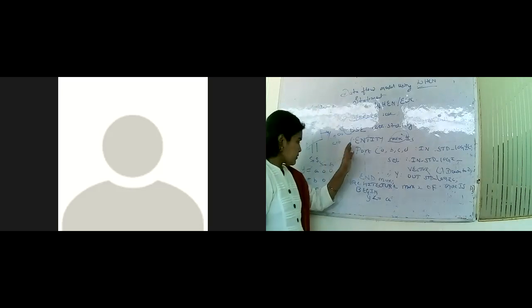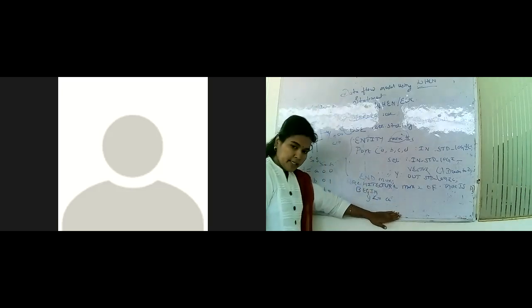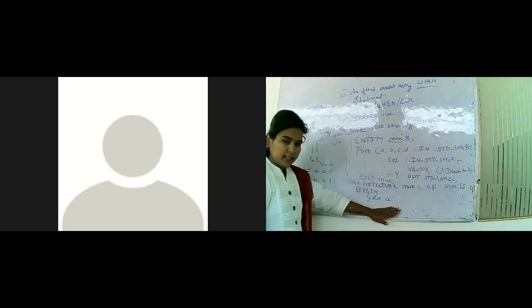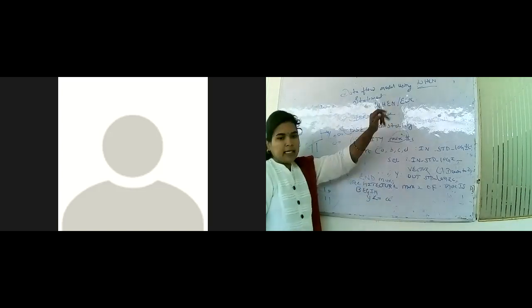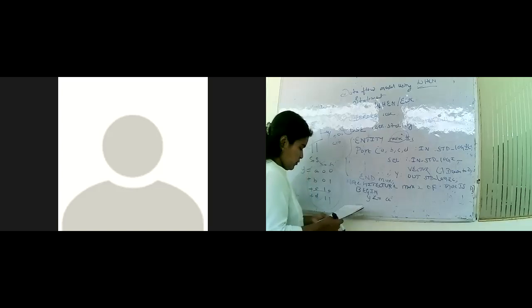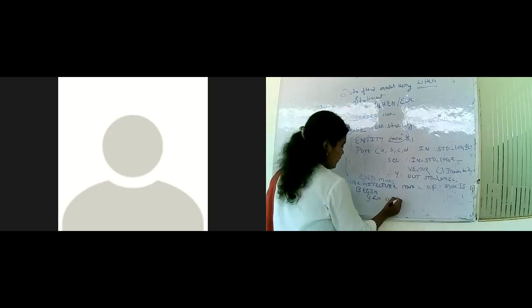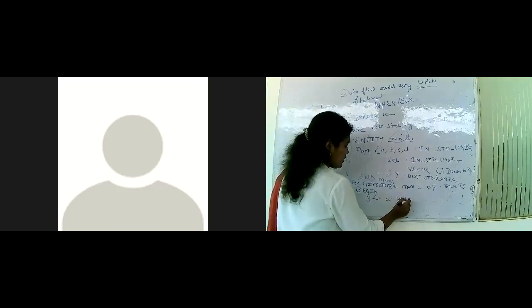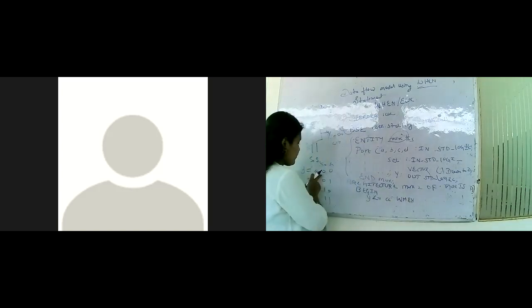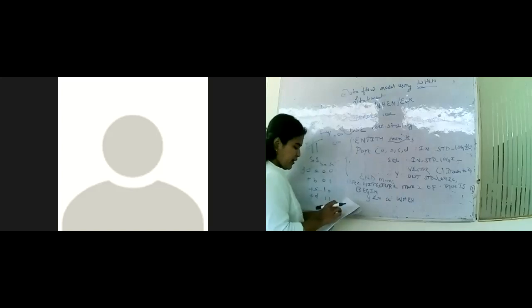While explaining logical operators, I explained this. So what am I writing now? I am writing the multiplexer output design in the when else statement format. So A will be when you have selection line as 0, 0.